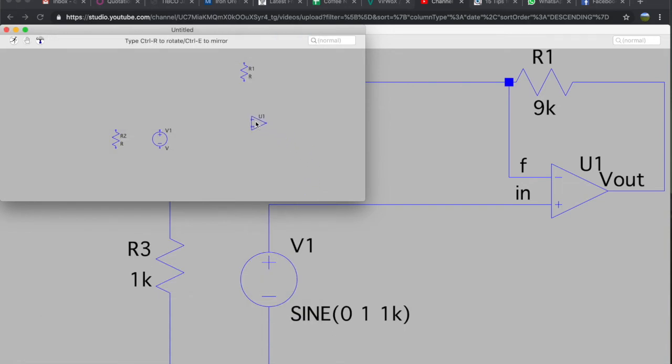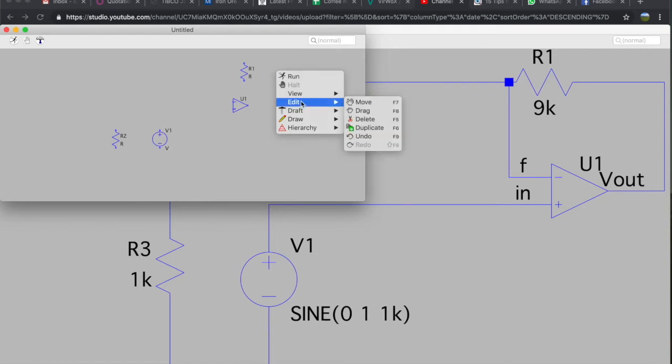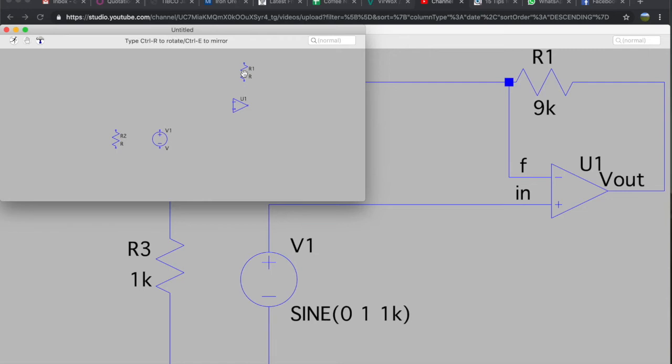And let's just place this over here. Once you select it, you can drag it around. Once you click, it'll set it down, and it'll automatically give you another one to place elsewhere. If you hit escape, it'll get rid of it. You can go look for a new component, or you can move or drag some other component. To do that, you have to go to the move command, and then come back and rotate it. On Mac, it's Control R, or Command R, sorry.